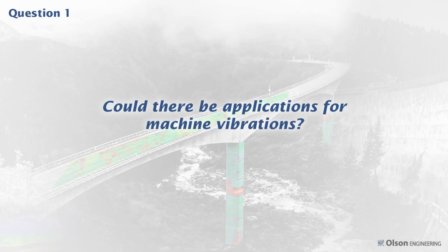Yeah. The first question is could there be applications for machine vibrations? I guess my answer to that is really large machines, yes. If it's a small machine sitting on a pad, it's probably better to do it with an accelerometer or a vibration measurement system. If it's a certainly large machine that it's hard to access, then it could certainly work. Thinking back, I one time did monitoring with seismic accelerometers on an ore crusher at a gold mine, and that was a large enough structure with columns and points that could have been measured.